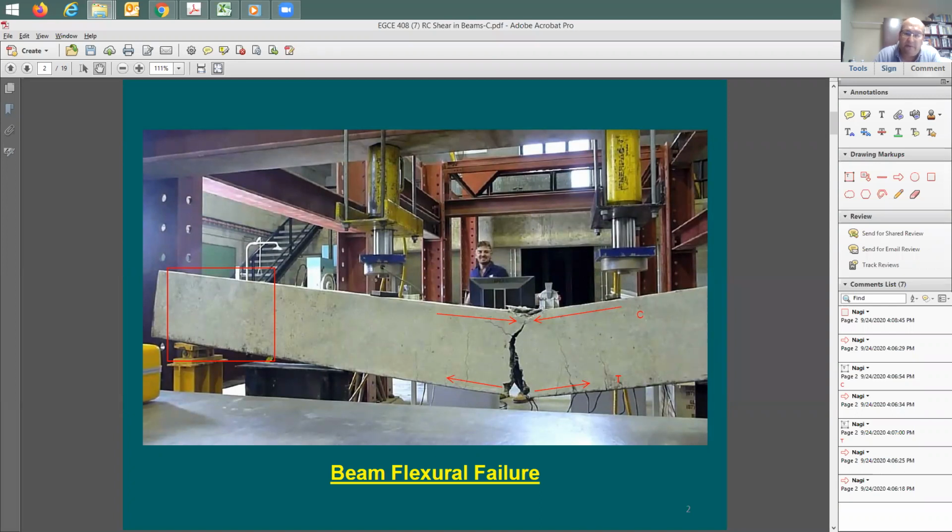Steel is good in shear if you're exposed to a shear, but the reinforcing itself is not exposed to shear here in our case. Concrete is very bad because it's a brittle material, right? And it's very bad when it comes to shear or tension.